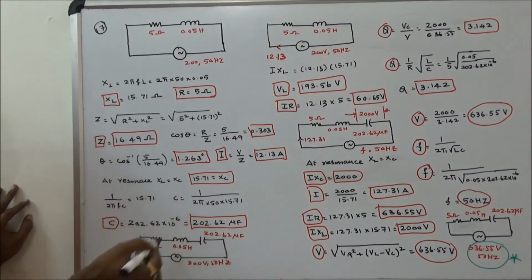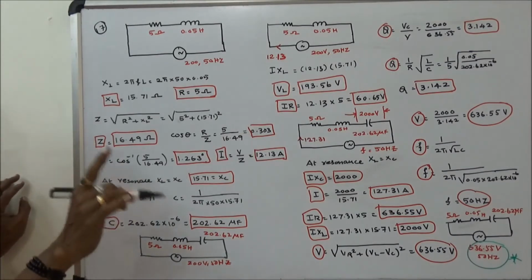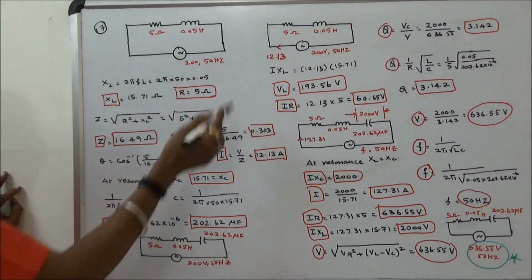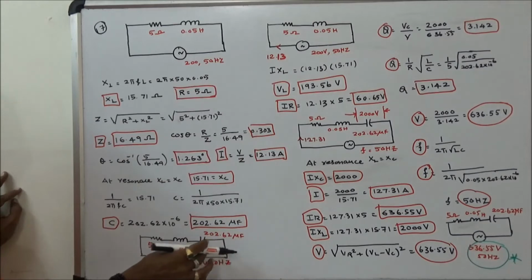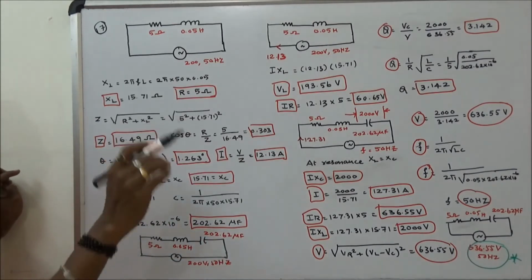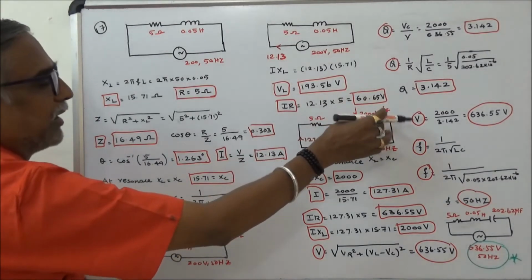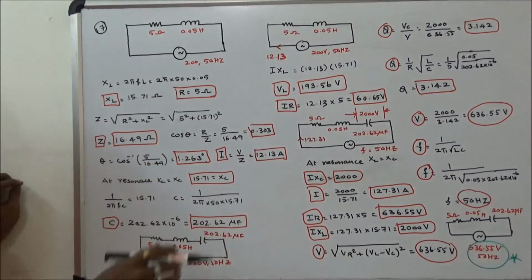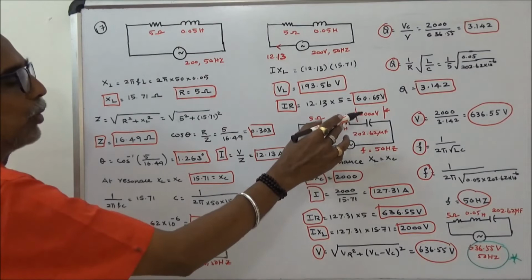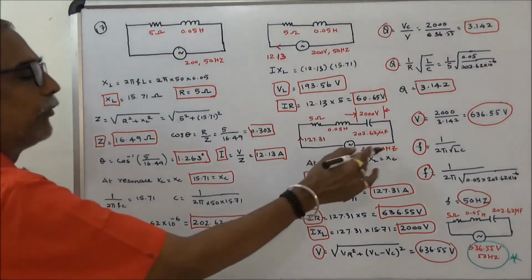with the inductor? In a resonance circuit, a circuit must consist of at least one inductor and one capacitor. So if resonance frequency is 50, what would be the capacitor to be connected in series with the inductor? The third question is, if voltage across the capacitor is 2000 volts, what would be the voltage to be injected in the circuit to get the 2000 volts across the capacitor? For resonance frequency 50 Hz.